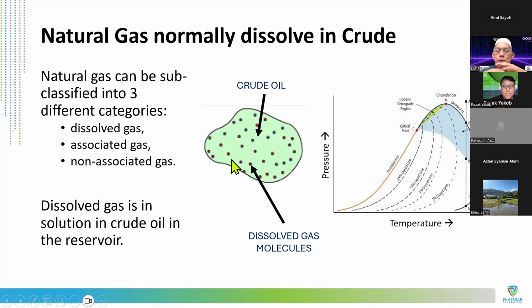So once it comes to a certain depth where the bubble point pressure or the flash point pressure is being reached or lower pressure, then the gas starts to be released from the crude oil. So you can see how even though crude oil still has some gas, in some wells we have a dry gas reservoir. Of course, the dry gas will come to the surface directly as it is,